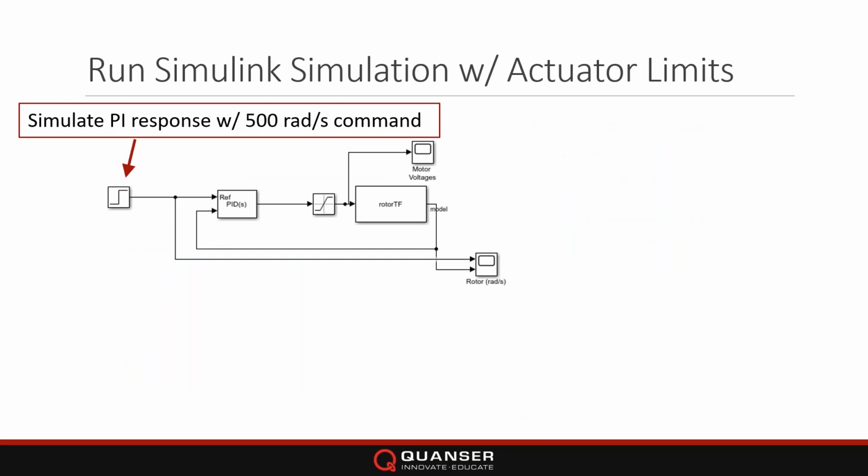So that's why we go to Simulink now and have a more realistic simulation. We're going to simulate the PI response with a 500 rad per second command. Okay, that's the first thing. So that's a major difference. It's a set point 500 times larger than the step command.